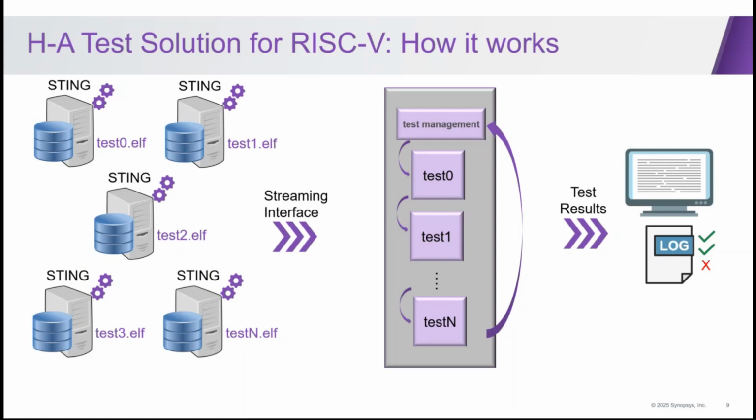In the traditional way, you generate the ELF, you load it, you reset your core, you run it, you shut down your core, you shut down your ZeBu, and reset again. So every time you run a test, it's from the reset state, a clean state, right? Now, you don't shut down when you move to another test, even another round.